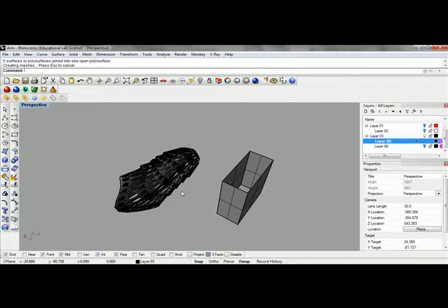And if you're going to be using an ABS plastic, a fused deposition modeler, you want to probably be in the range of at least 1/16 of an inch, if not the same tolerance of 0.09 inches thick. The reason for that is if you get too fine, when it slices the layers on the FDM machines like a Dimension or Stratasys machine, it won't calculate that properly, and you'll get pieces as it goes through.